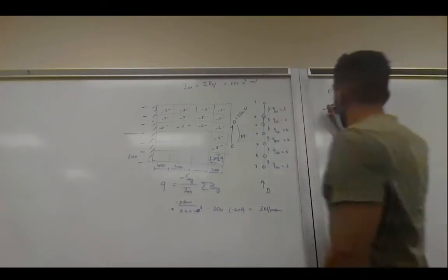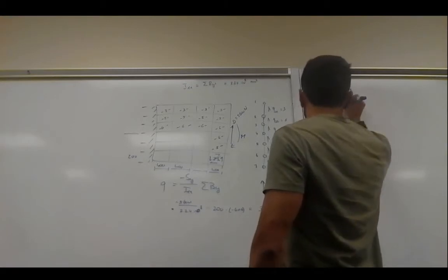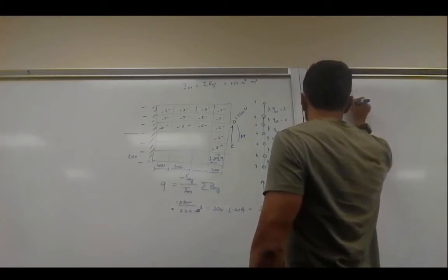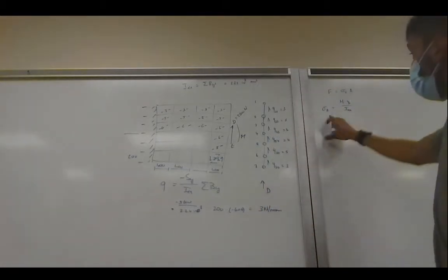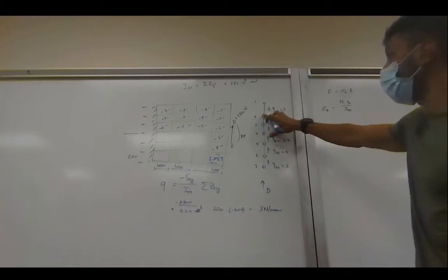So the stress we get by saying the moment times y over Ixx. And now we use the moment to determine the stresses in each of these booms.